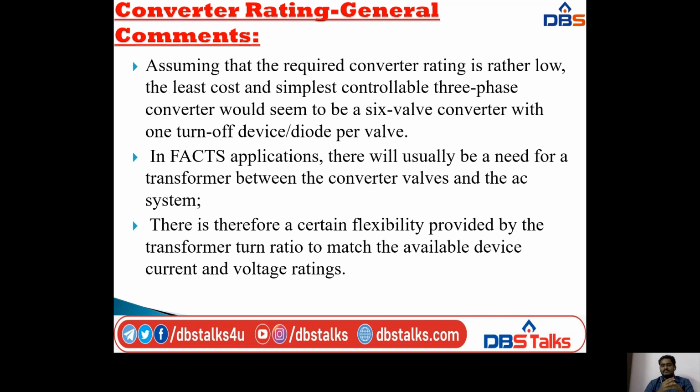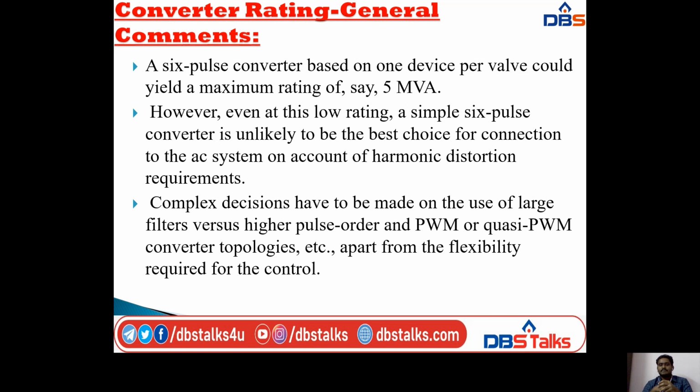That's why we are using the transformer turns ratio. It will give flexibility. Next, a 6-pulse converter based on one device per valve could yield a maximum rating of, say, 5 MVA. Here I am taking a 6-pulse converter based on one device per valve.